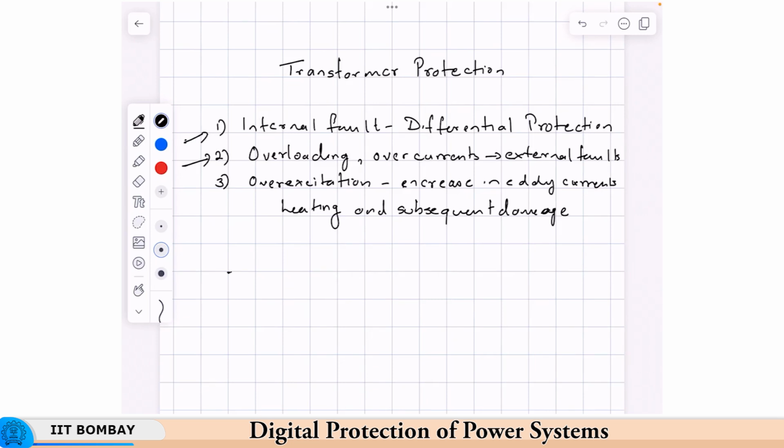We will look at an example of a transformer in this class of course, but we are just talking of some network element. It could be a transformer, a motor, a generator, anything. So, this is that network element, say some element E, which needs to be protected using differential protection. We have the CTs on both sides to measure the currents.